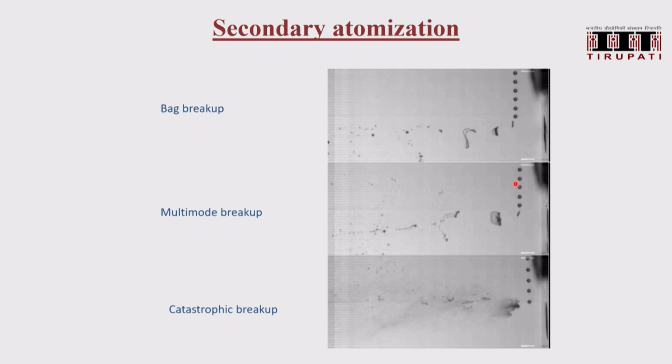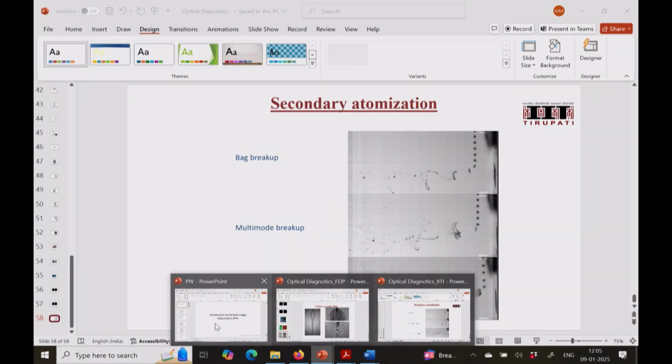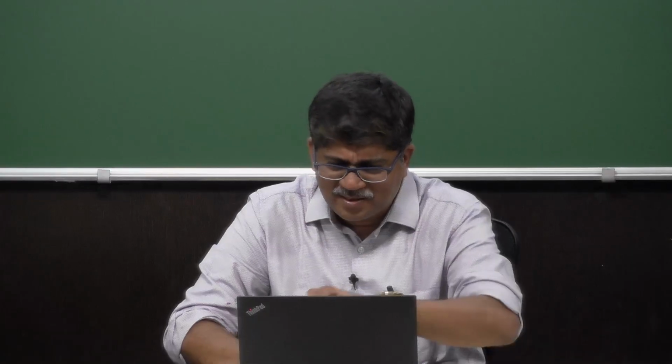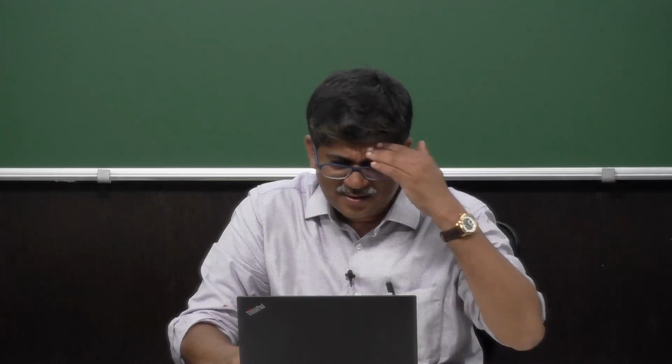The other thing is, if the spray is too dense, that will also be a problem. That's why measurements are usually made sufficiently far away, where the spray is not optically dense. That is the term used. So this is about spray diagnostics. Probably I'll give a quick overview of particle image velocimetry, especially. Quite a few of these topics I already covered, so I'll quickly go through this.